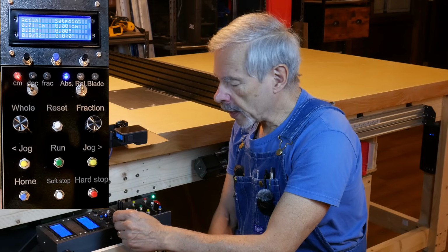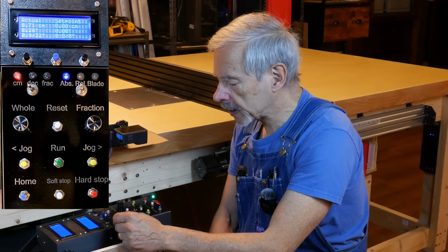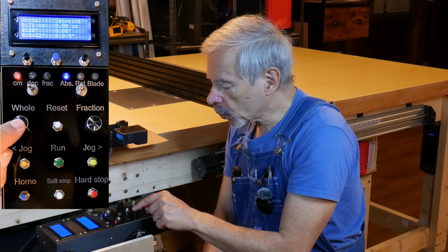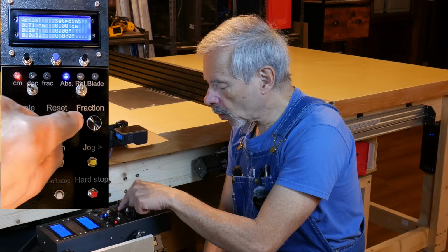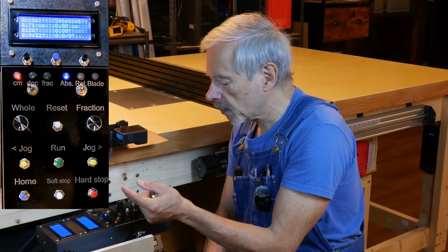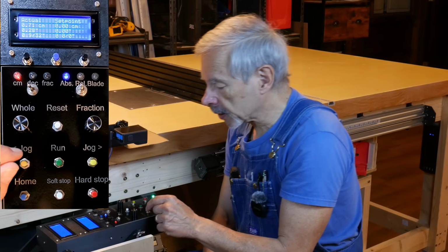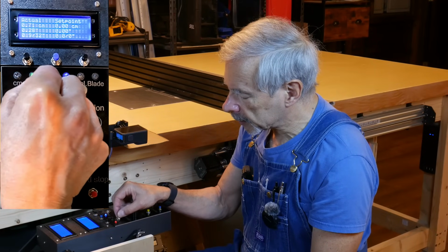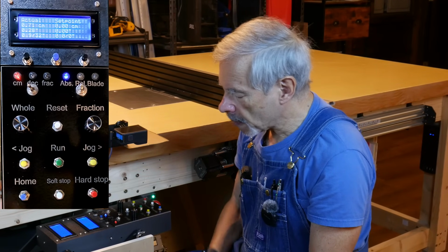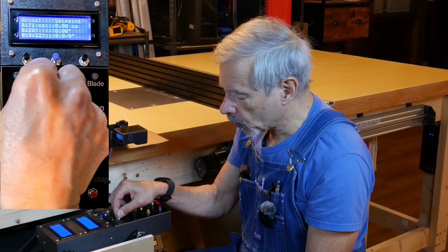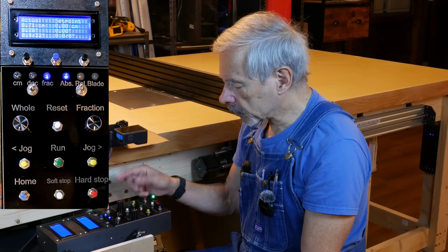notation. So if I want to go ahead and set the set point to 30 inches, I use one of 2 encoder knobs which are labeled whole or fraction. The whole sets whole numbers of units, and the fractional encoder knob sets fractional parts of the set point. Also, I need to explain that there is a 3-position switch that allows me to choose in which type of units I want to enter the set point. In this case, I want to go to inches in fractions, so I'll go right ahead.